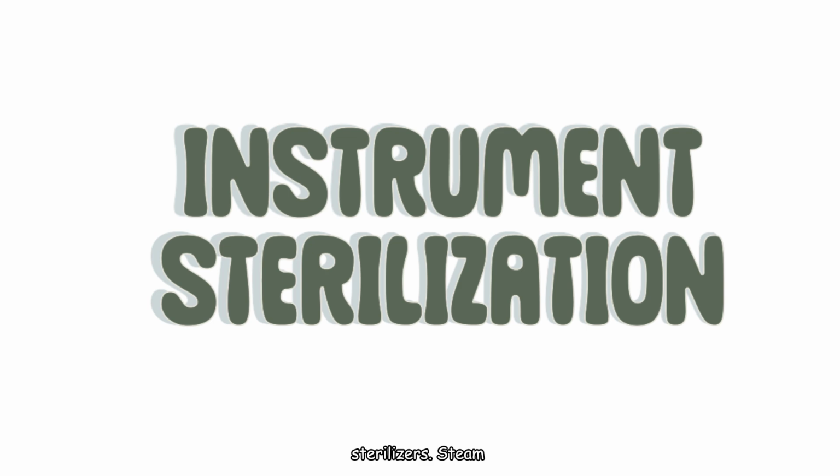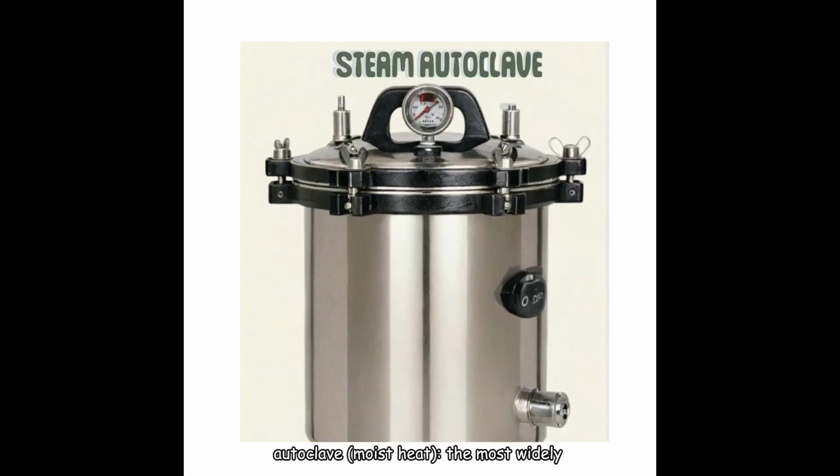Steam autoclave, moist heat, the most widely used method, utilizing high pressure steam to kill microorganisms. The standard parameters for steam sterilization are 121 to 135 degrees Celsius, 250 to 270 degrees Fahrenheit for a specific duration, depending on the type of autoclave and load.